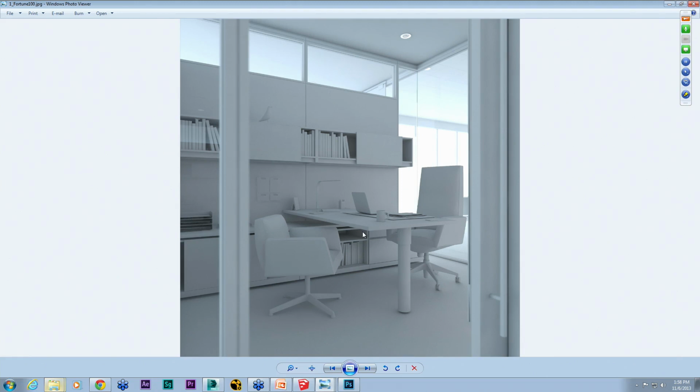I think it's like a 0.2 in V-Ray's actual GI settings. And then once we get that right, and we've got the DOF and everything here, then we will start adding other lights, really subtle. Right here I added the lights for the exterior. And let's see if it shows a difference there. No, okay. So then we'll add the interior lights right here.